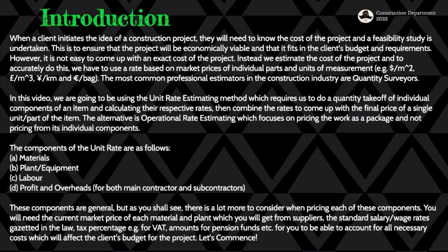Overheads are basically the costs that may arise during the course of the project, like taxes and the like, just those costs that are indirect, not the direct costs mainly that are really related to construction, but other costs that may also affect the project, like the tax that I was talking about. You're going to see when we deal with quotations, we have what we call value added tax, VAT, and then we have pension funds for the workers.